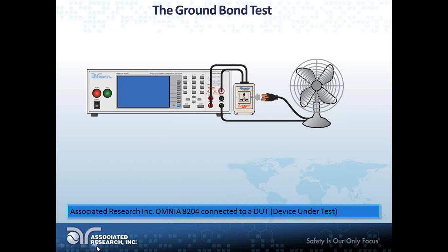This particular setup would be designed for a ground bond and HiPot test to be run sequentially. In this case, we don't care about the HiPot connection, but as you can see, it's there. So what's going to happen is you're going to get current generated from that red terminal. It's going to go through to the adapter box. The current is injected on the ground pin, and then it's looking for the return path on the chassis point